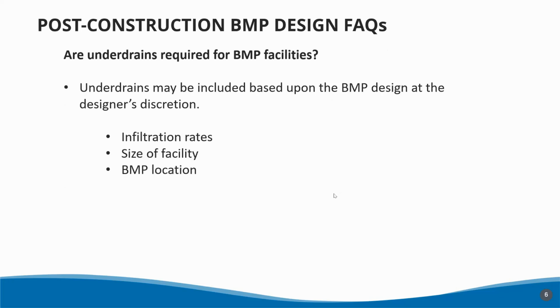And are underdrains required for BMP facilities? This is also based upon the designer's discretion and their experience. When you do include underdrains, you need to look at several factors, including your underlying infiltration rates and the size of the facility.